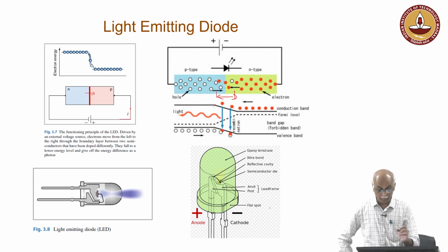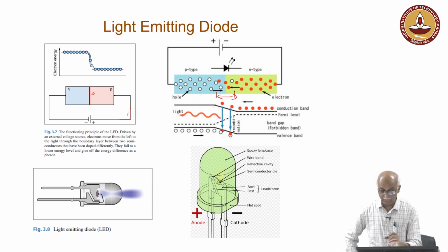Now, see in terms of Fermi level, what it means. Fermi level represents the probability of an electron being present, around 50% or more electrons presence at that level. So, here you can see in n type the Fermi level would be located near the conduction band, because the probability of electrons will be large, and in p type it will be near the valence band.